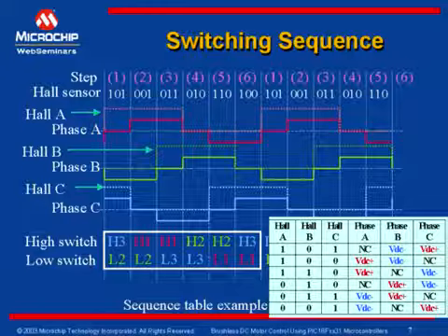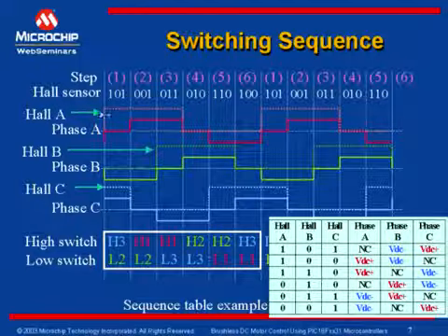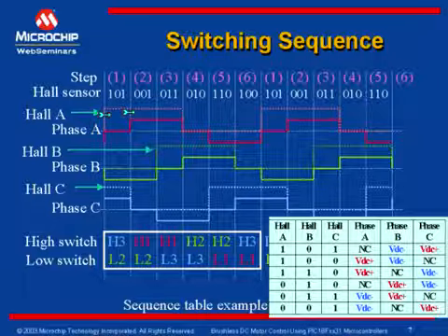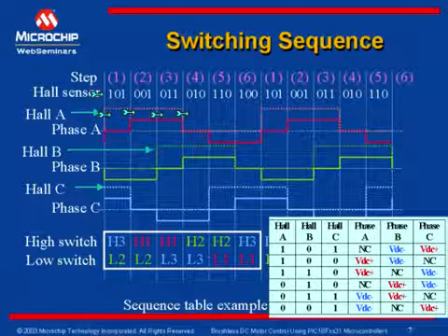With 3 Hall sensors on the motor, every 60 degrees of electrical cycle, a Hall sensor makes a transition either from low to high or high to low as seen here. Every 60 degrees, a Hall sensor makes a transition at this point, and the Hall sensor sequence changes from one to the next. With this, every electrical cycle has 6 steps to complete one full cycle. That is 60 degrees per sequence, so 6 steps per 360 degrees of electrical cycle.